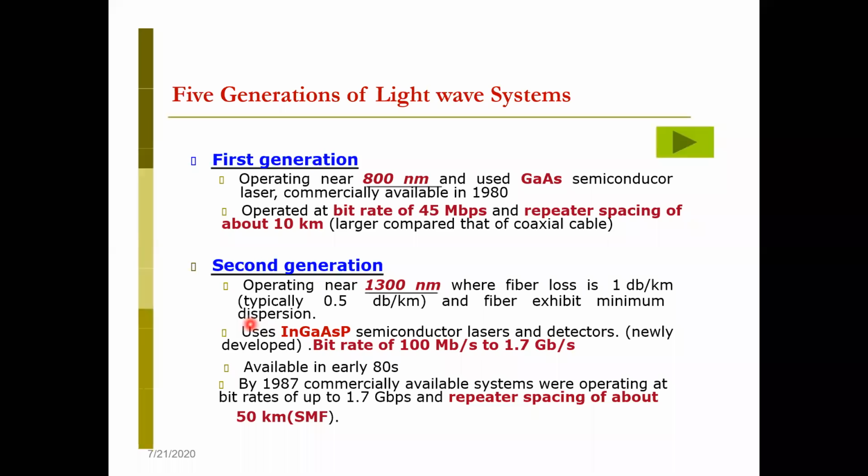You might not be able to recognize whether it is 1 or 0. Suppose there is a 101 signal. The 1s disperse so much that they merge in the middle, so that you don't recognize that there is a 0 in between. You might feel that the signal is 111. So that is your dispersion. Don't worry, we will see all this in detail. My pulse width increases, so that is my dispersion loss.